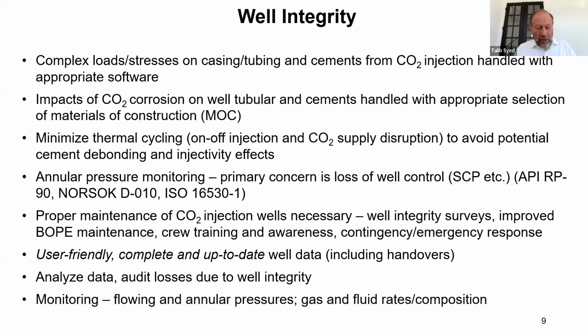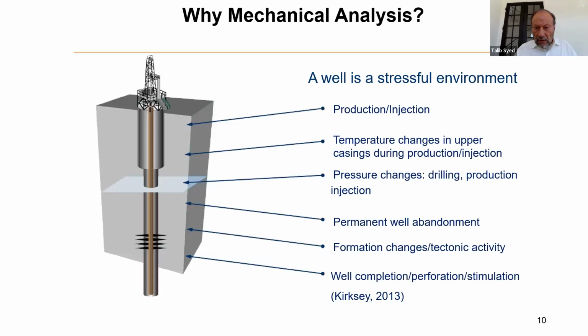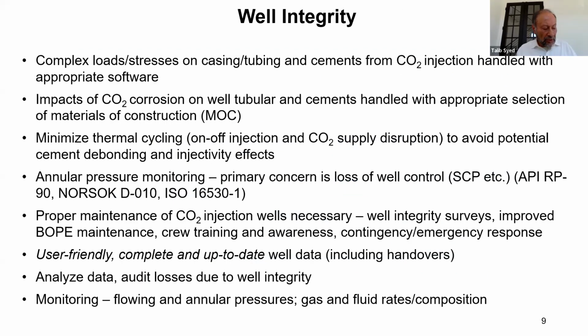So there was a mention in today's morning sessions about fault activation and fractures, etc. So it's very important. When you've got high injection pressures with low injection fluid temperatures, it can induce hydraulic fracturing. So you've got to have geomechanical models to determine the in situ stresses and the fault activation hazards. When you locate CO2 storage wells, locate them as far away from faults. So in your screening model, if there are faults, if there are fractures, those are not good sites for siting your CO2 storage wells.